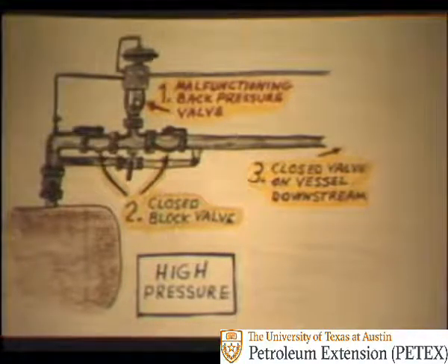The final problem we will discuss is that of high pressure in the separator. This also can be caused by a malfunctioning back pressure valve, or one of the back pressure block valves may be closed, or a valve to some vessel downstream may be closed.